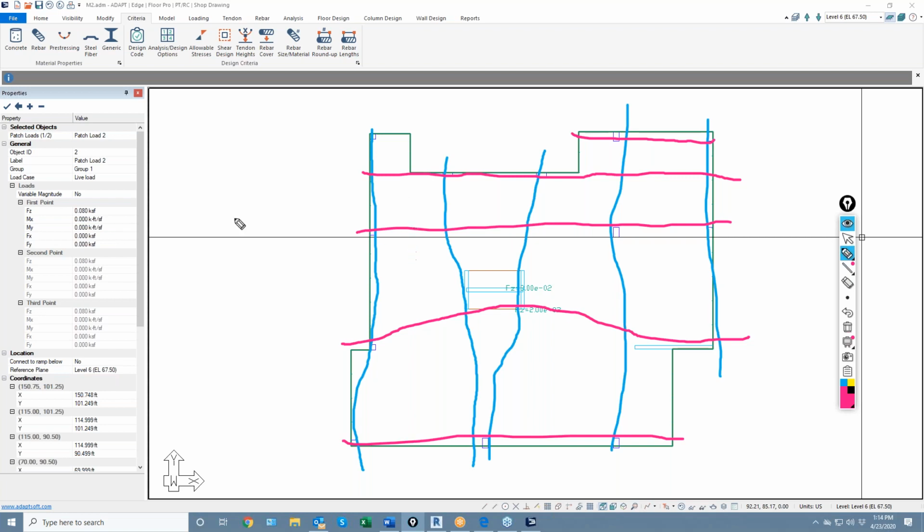So if I have a 4-foot section here, this is 48 inches, and I say I want to target at least 125 PSI pre-compression for this unit section, by calculation we need 1.7 some inches or cables per 48 inches. You can actually enter that into the program. You could have a cable that's in decimal format. It's not a whole number.